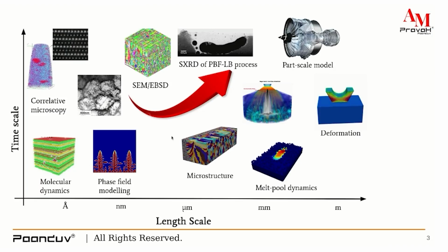AM PravaH works on a scale of micrometer to meter scale. At micrometer scale, you use synchrotron-based X-ray imaging techniques to have a deep understanding of transient behavior of the melt pool dynamics. And you also perform SEM or EBSD analysis to have a better understanding of the microstructures.